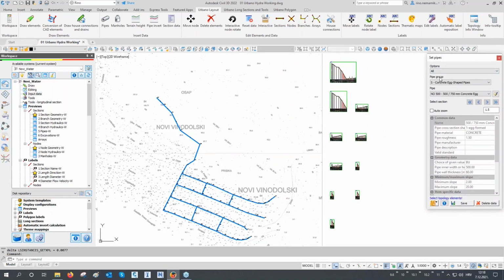And here you can see that you can select a pipe group, all these pipe groups that I showed you in the catalog. So here is also the new group that we created, my ductile iron pipes, but I would like to use PEHD pipes. So I will use this pipe. So these are water PEHD pipes with the nominal pressure 10.